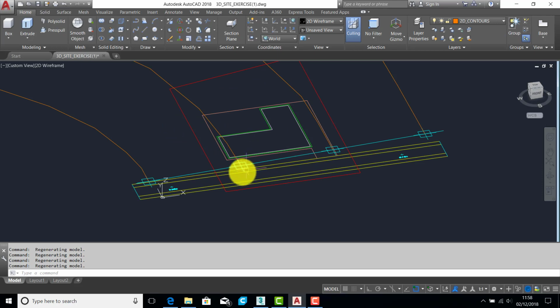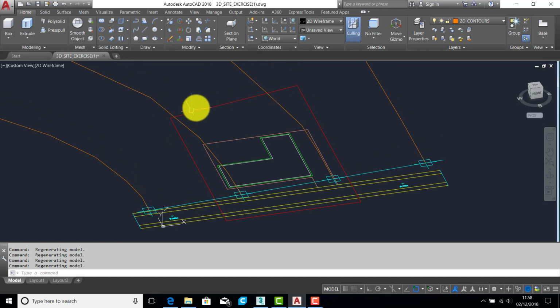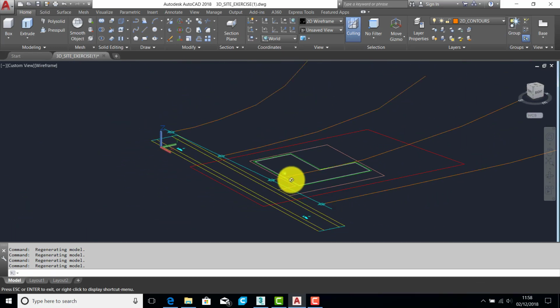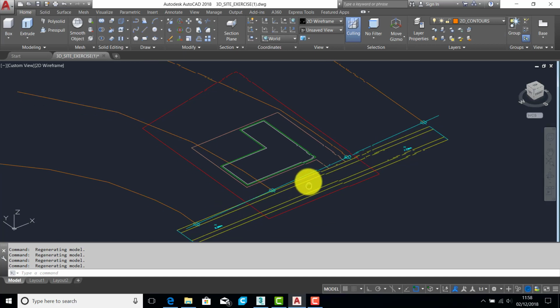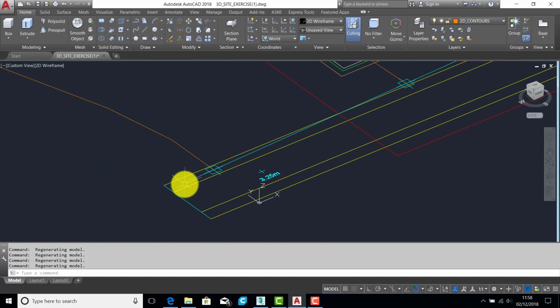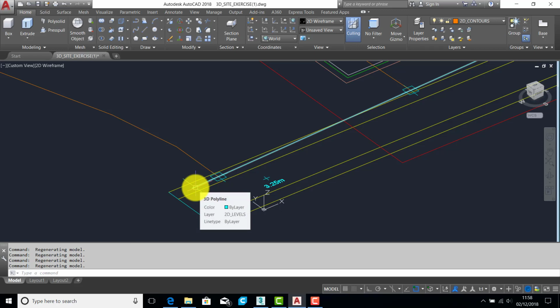Okay, and the purpose of this is so that we can establish the boundary of the site and find out the height of the land at the boundaries, so that we can model the edge of the site properly. Okay, so we've got the blue line is effectively the boundary line on this side of the road, so that's an even slope. So we can use the line itself to help us set up this. So this is what we'll say is that this will be the edge of the site, okay, and then the roadway will be slightly lower than that to give it a bit of form.